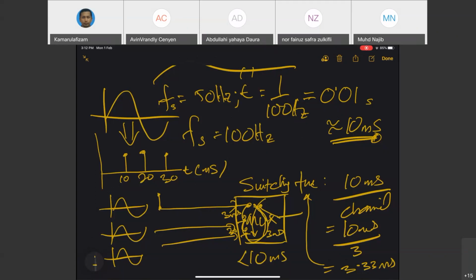All right, meaning that from the first switching time, switching through all of the inputs until it goes back, it has to be less than the sampling time. This one has to be less than this, because when you finish, you need to look at the next input, which is 10 millisecond, 10 millisecond, 10 millisecond. Also the same for this one too, all right?